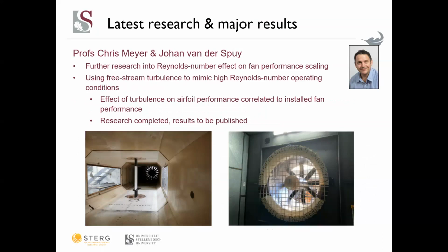So these researchers do more research. They're looking into the Reynolds number effect on fan performance scaling. Normally when you have a small scale fan, the Reynolds number across the fan blade is not the same as for a large fan in the application. They are doing research in order to mimic the high Reynolds number operating conditions on small scale fans. They do this by using the effect of free stream turbulence on airfoil performance, which they then correlate to an installed performance.